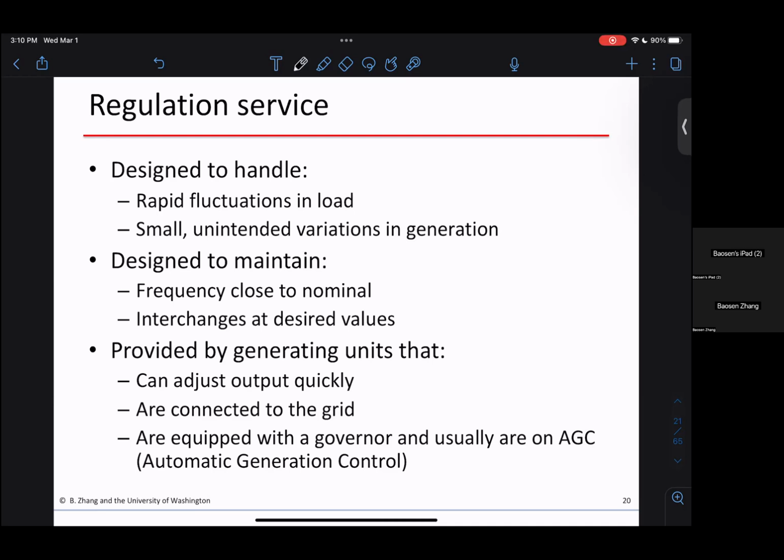Batteries, right? For many markets, this is now cornered by batteries, because what happens here is these are zero mean, very fast fluctuations. So your battery, this is actually your favorite application. You don't need to generate anything net, you don't need net generation. All you need to do is respond. 4 seconds is extremely long for batteries. A battery can respond in sort of 4 milliseconds. So this is very good for batteries.